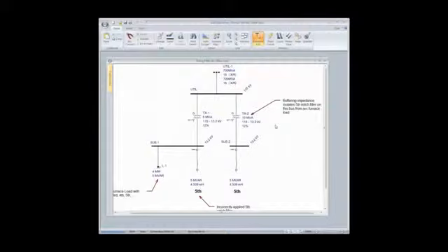Where do you tune it? Given the proliferation of 6-pulse drives and multi-pulse systems out there, obviously the fifth harmonic is a key point that we're all very familiar with. But that's not necessarily the best place to tune. Where you want to tune is what we'll consider the lowest characteristic harmonic of the particular load or loads that you're trying to reduce distortion with or avoid resonance with.